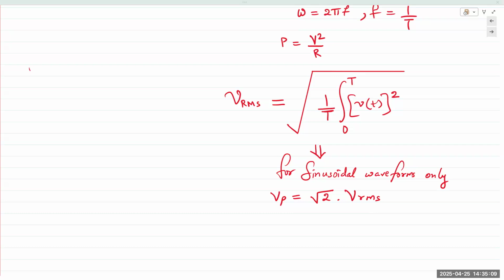Anyone with a value? It's approximately 170 for 1/2 cycle. So that's a peak value of 170. Did anyone else get 170? 170. And so peak to peak would be 340 volts.